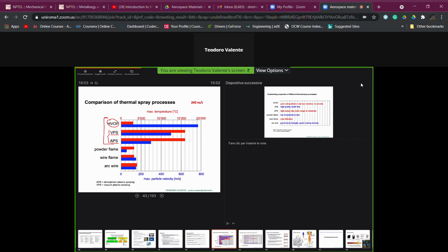Instead, if we need, or if we select, to spray metallic alloys, nickel, chromium, boron, silicon alloys, for example, in that case, the question of which of the two technologies must be used to have a better coating quality is worthwhile to be discussed, because metallic alloys can undergo oxidation phenomena if the molten particles see oxygen before coating deposition.